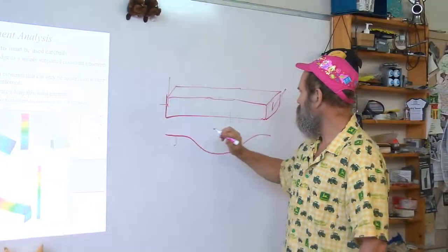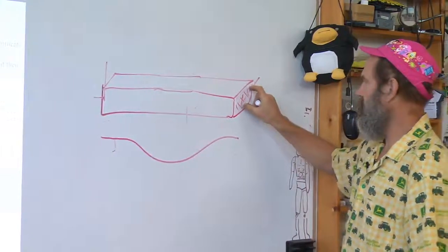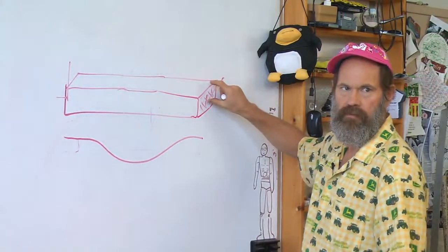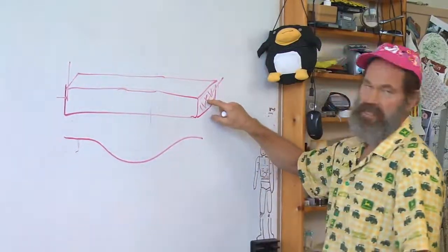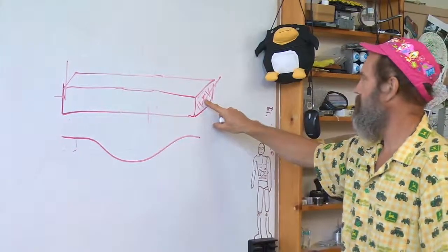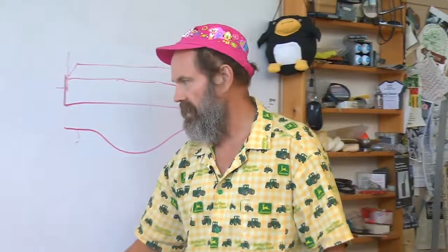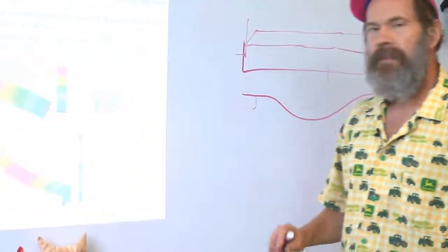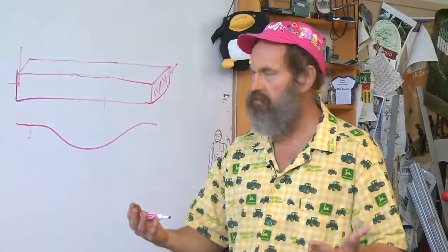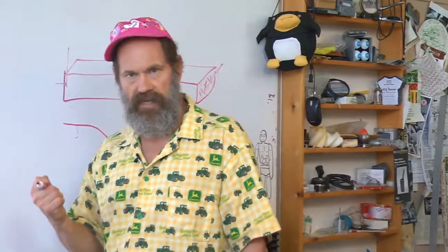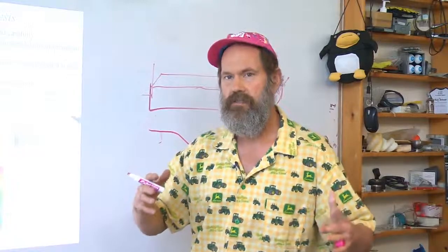In other words, if you check a surface to be constrained on a solid, it doesn't allow any rotation. Even though you know when you're putting your beam in your machine, it's not being held infinitely rigid. So this is wrong. The beam is not going to bend like this. It's okay when you're designing your layout and you know you're going to be doing finite element analysis. Remember, you want to visualize the structure and how it deforms, what it does.